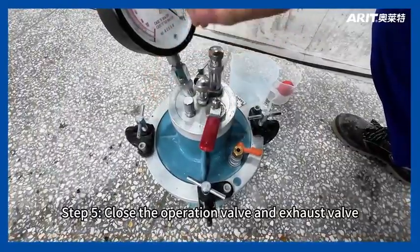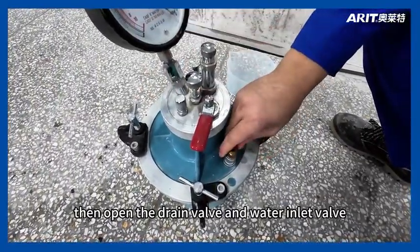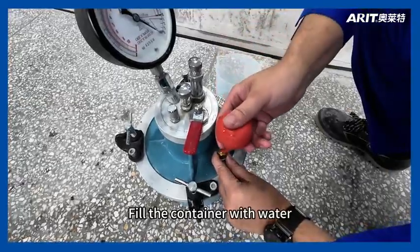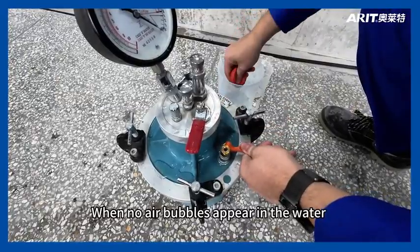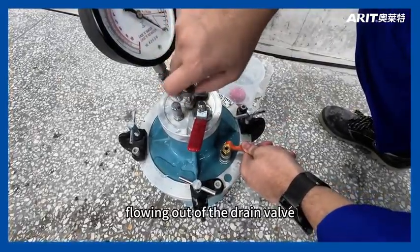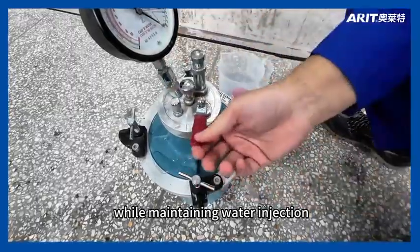Step 5. Close the operation valve and exhaust valve, then open the drain valve and water inlet valve. Fill the container with water through the water inlet valve. When no air bubbles appear in the water flowing out of the drain valve, close the water inlet valve and drain valve while maintaining water injection.